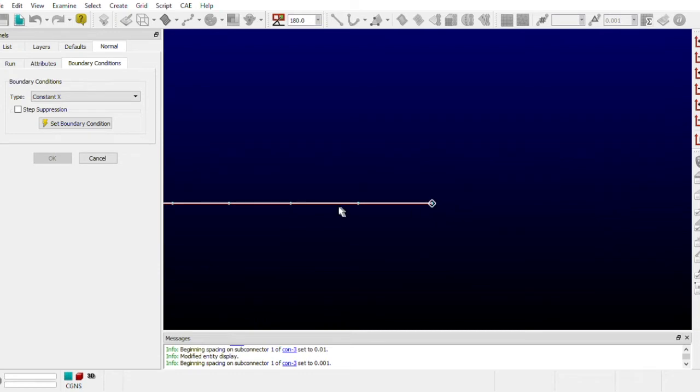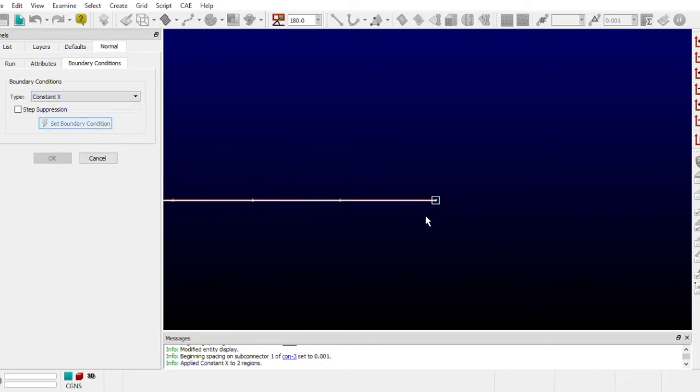If you don't do that, it's just going to splay out outwards with all the after effects without being constrained in a boundary, in a box. So instead, we'll click on that point and select constraint X. Then when I set the boundary, it's fixed. So later on when I extend that section, it's easier for me to create a box.